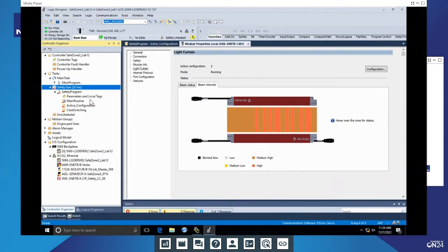Exactly. That's right. And to add to what Dan said, because safety is the most fundamental task, another thing that we have is your safety program is password protected, and you need to make sure that only certain people know this password. And secondly, every safety device, whether on the backplane or on your Ethernet node, is given something called a safety network number.